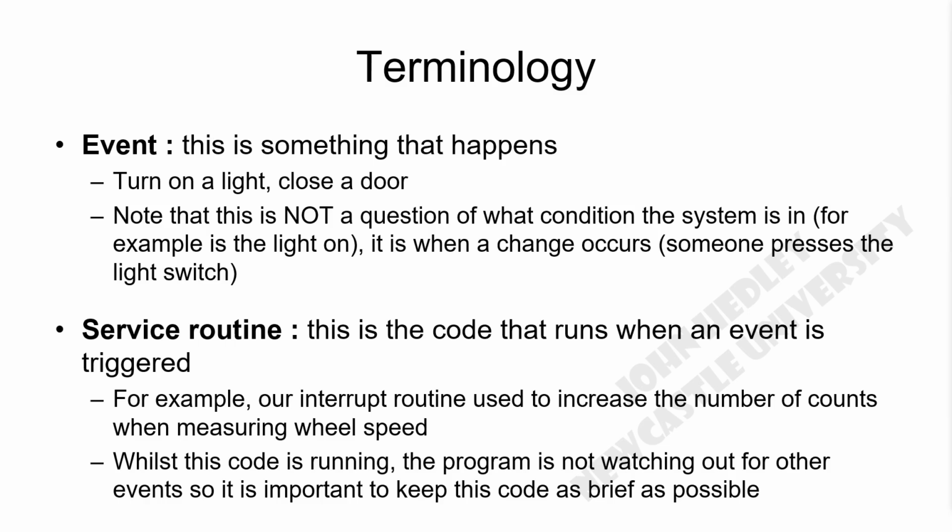It is very important to keep our service routines as short and quick as possible, because when they are running, they are not looking out for other events that may be occurring.